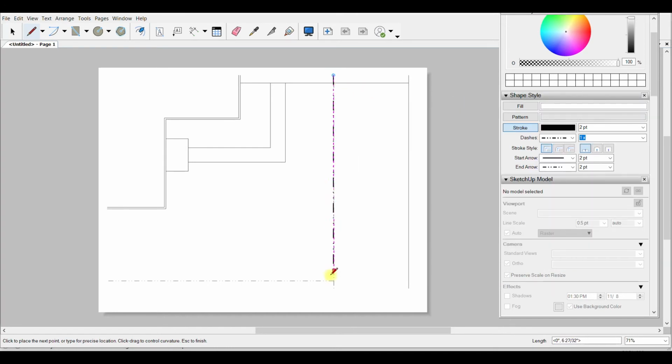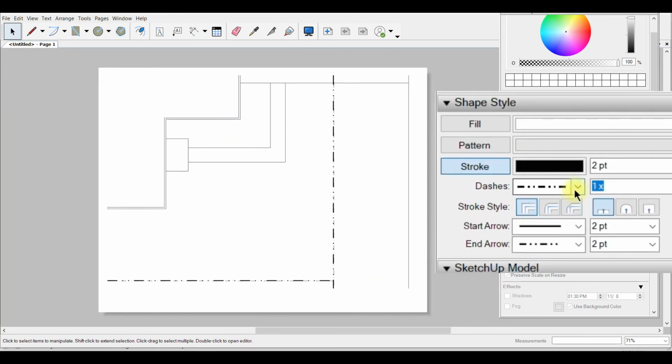So I'm going to snap to there and snap to there, snap on there and up to, that's my property line. There is no line here. That doesn't exist. More importantly, we want to get a solid line here. We're going to make it a width maybe around 8 and enter. We can type much wider widths in there if we want to. And we're doing line. So it's 8 points wide, it's solid, it doesn't have any arrows.